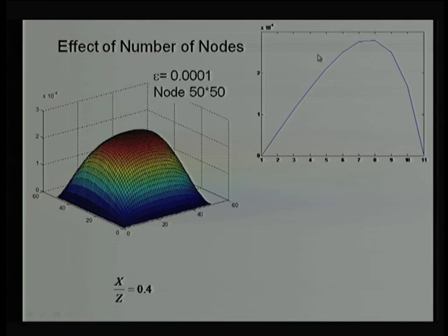We calculated using approach 1 by neglecting the second term, and we evaluated the non-dimensional pressure profile. I am talking about the maximum value of the non-dimensional pressure, which is roughly 1.5, 1.6 here, while there it is coming around 2.8. There is a significant variation.